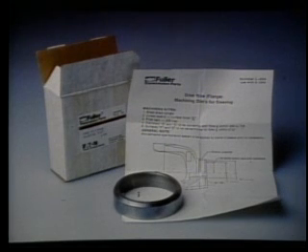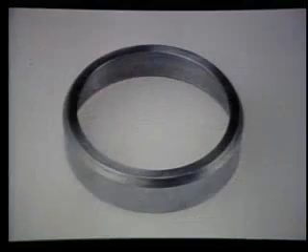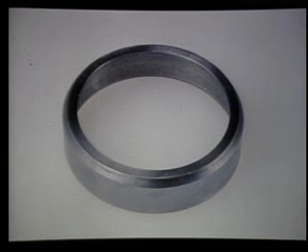Wear sleeves that increase the yoke seal surface diameter can cause the seal to wear prematurely because of increased seal lip pressure. The sleeve included in the K1940 is a heavy wall construction with a hard chrome-plated seal surface. The outside diameter of the Fuller sleeve is the same as the original yoke diameter and will result in maximum possible life for the replacement seal.